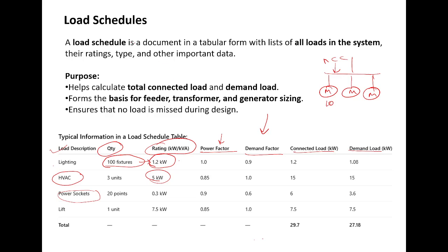What is the purpose of these load schedules? It mainly helps to calculate the total connected load and demand load. It forms the basis for feeder, transformer, and generator sizing, and we'll discuss later how it helps. It also ensures that no load is missed during design.